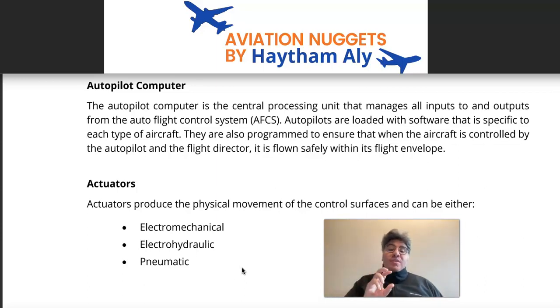And remember always, push to manage and pull to select. When you pull the selector and rotate, you as a pilot give a certain heading, altitude, or vertical speed to the autopilot. So the FCU is used to allow the pilot to assess the situation and give input to the autopilot computer regarding speed, heading, and altitude.